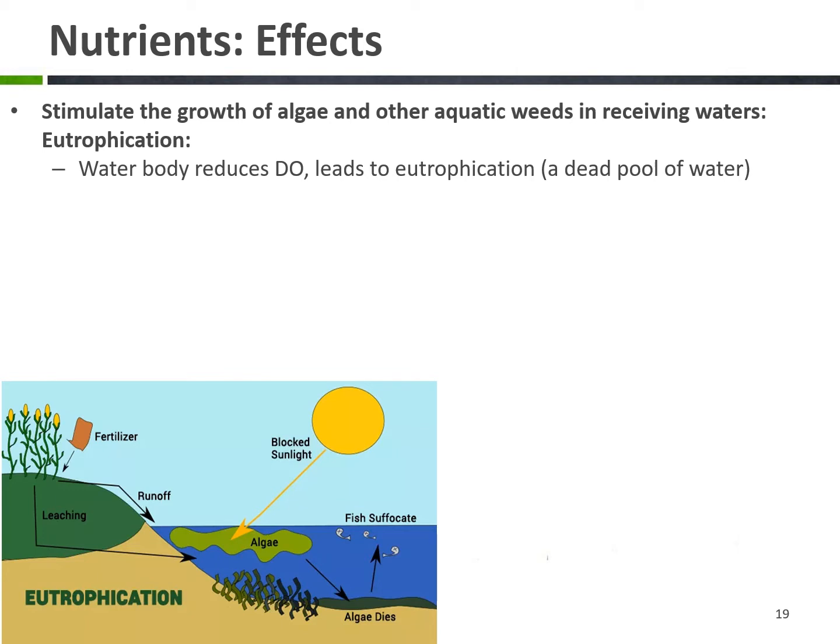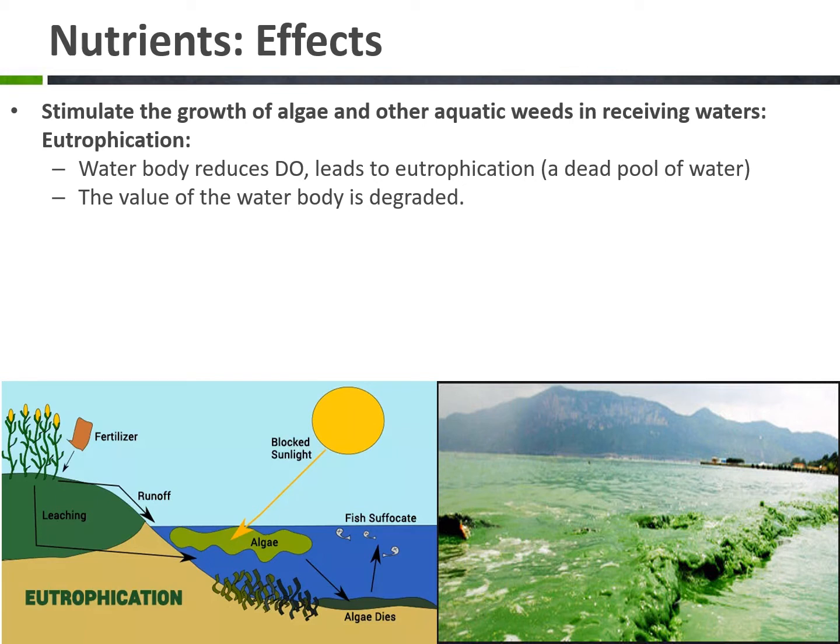At the same time, the top layer algal growth will gradually settle down after the completion of the growth curve, which I think you already know. Because of the continuous growth of algae in the top layer, finally the algal growth will start filling up the whole lake, and gradually the whole content of algae will start dumping in the bottom of that lake or water body. So this is the concept of eutrophication. Please go through this phenomenon as well, eutrophication.